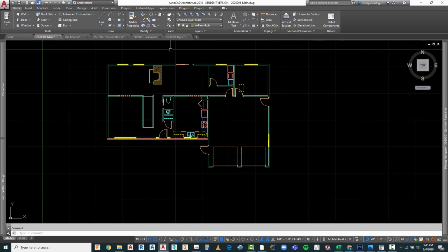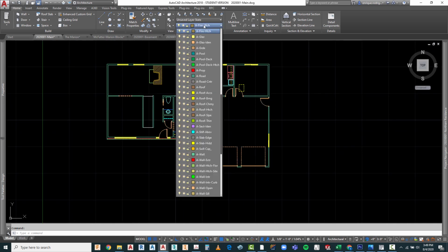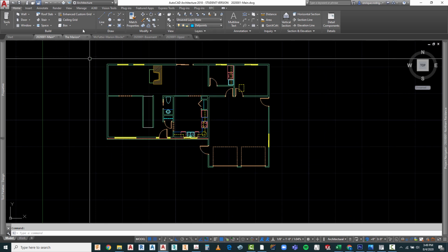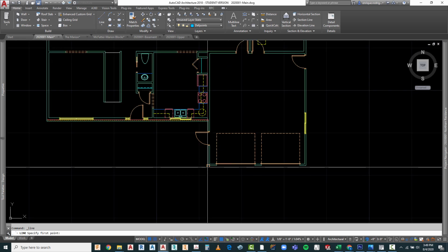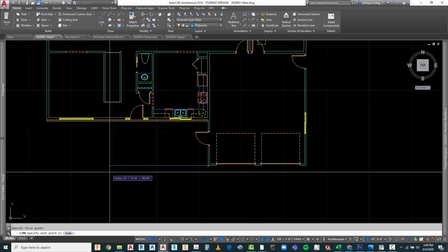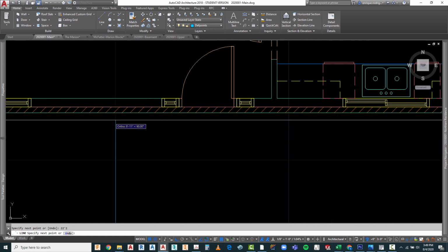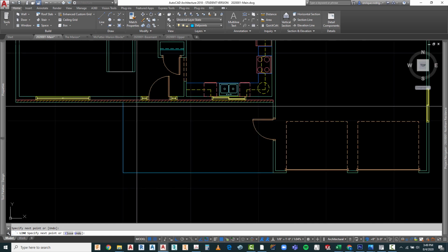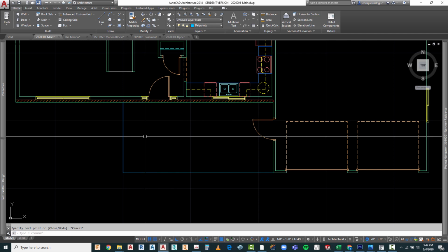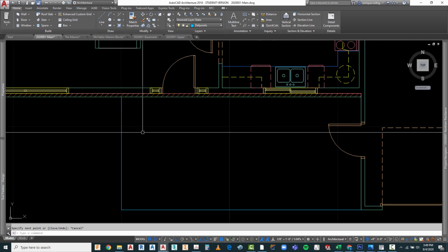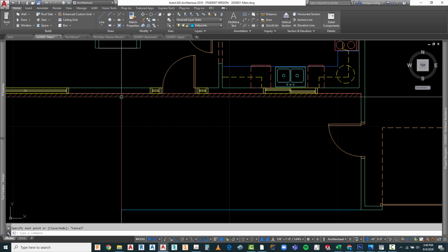So the first thing I'm going to do is, in a construction layer, in this case I can just use a depth point layer, I'm going to go ahead and draw a line from this corner over 22 feet 2 inches, and then another one that's going to go back to our brick right there at that point. So that's what we've got laying out in there.